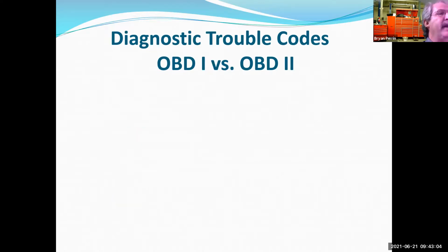There was a real battle over this in the 90s when we were coming out with this new technology, and I was going to classes and coming back and saying, hey, the guys in the shop are doing this wrong. OBD2 has no soft codes. The two types of codes are soft codes and hard codes. A soft code is kind of an intermittent code. It's not always failing. A hard code is like a wire shorted together. It's shorted, it's not going anywhere, it is bad all the time. A soft code would be a wire that touches sometimes.